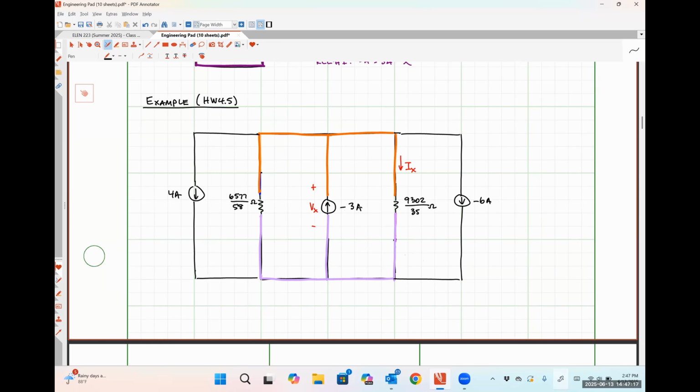Okay. So I'll write it out a little bit more instead of just doing it to you. Okay. So I have -3 amps up. I have -6 amps down, and then I also have +4 amps down. Those are all of the different directions and magnitudes of my currents that are connected in parallel. I'm choosing up as my reference direction. So I'm saying that anything that's flowing up is getting a positive sign, and anything that's flowing down is going to wind up getting a minus sign.